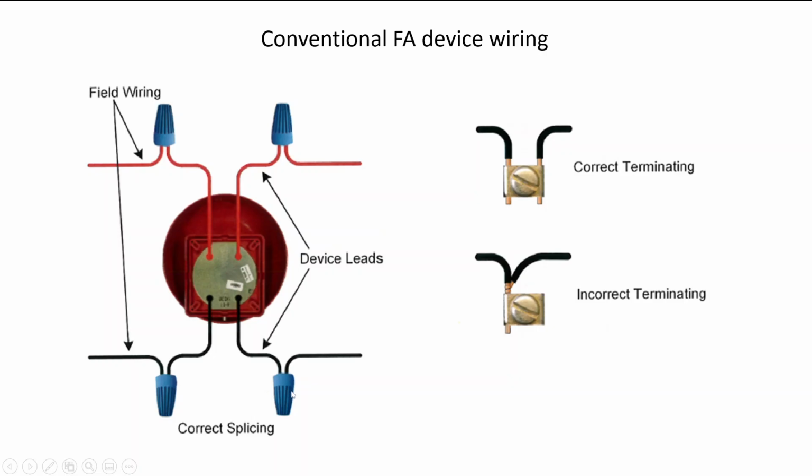We don't just take one wire nut and tie all 4 wires together, although that's what you would do with a receptacle. Instead, we keep each one independent, so that if someone were to remove the bell, they would have to interrupt the supervisory current of the line conductors here, and that would trigger the fire alarm panel into trouble. In the same way, when we have terminals on the back of a device, you're not going to twist them both together and then insert them underneath one side of the screw, but they must be left independent.